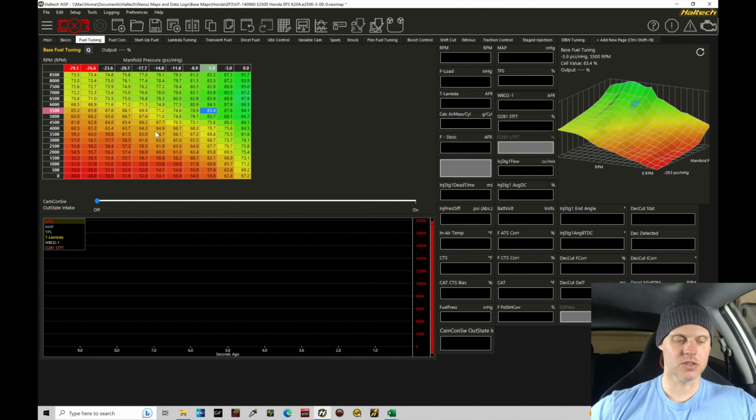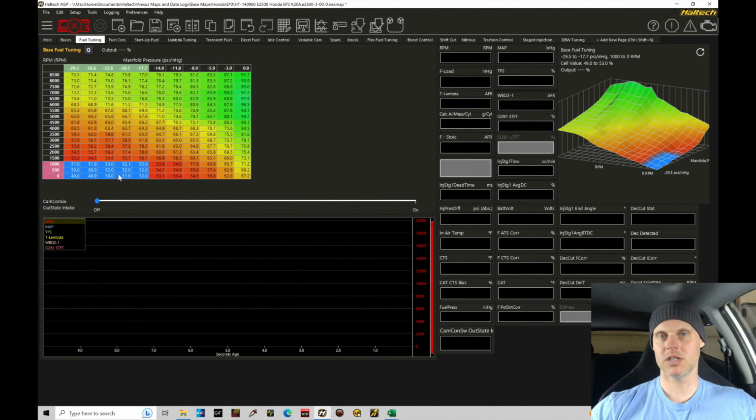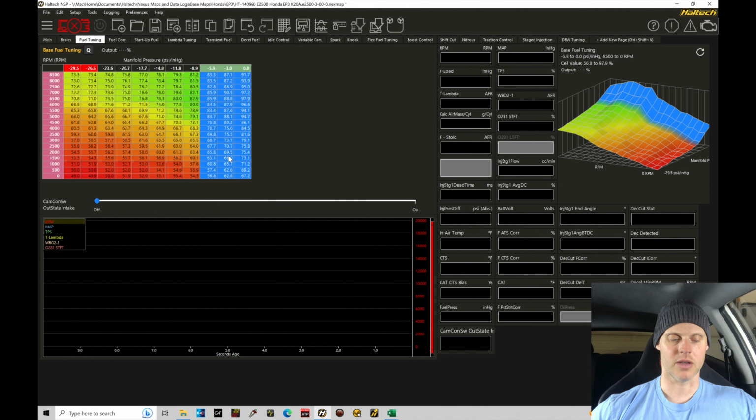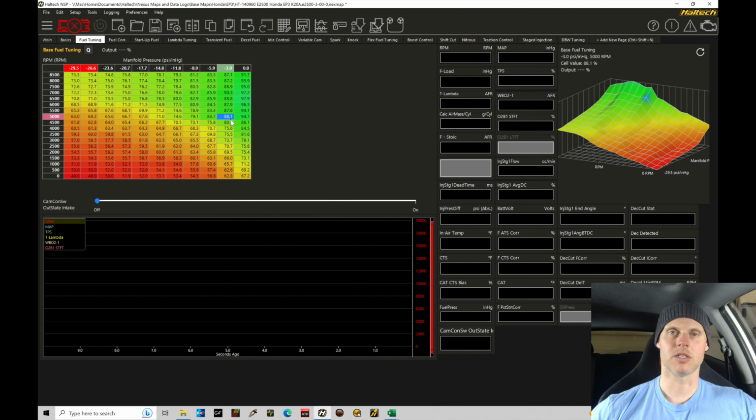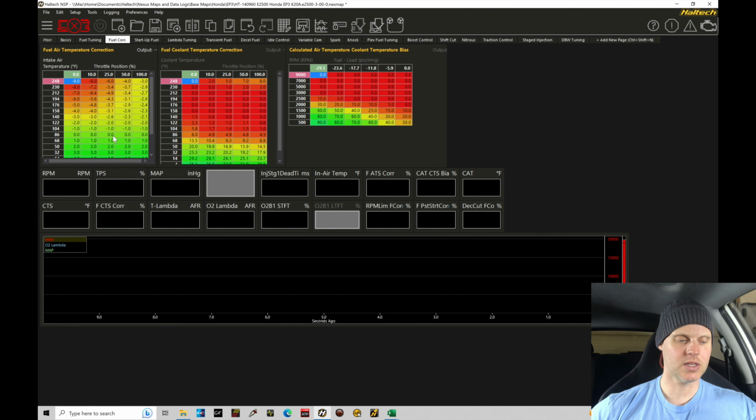Now looking at the values in the table, at idle here, values are roughly 50% VE. 50 to 60 is typically what we want to find here in the table. When we're at full throttle, in the last 3 columns getting into high load, values go from 60 to 90, pretty reasonable as well. That's about what we'd expect. We're going to run with the values in our table here and see what happens. So we're not going to do any further changes in here. Let's go to our fuel corrections. We can see in this case, the air...